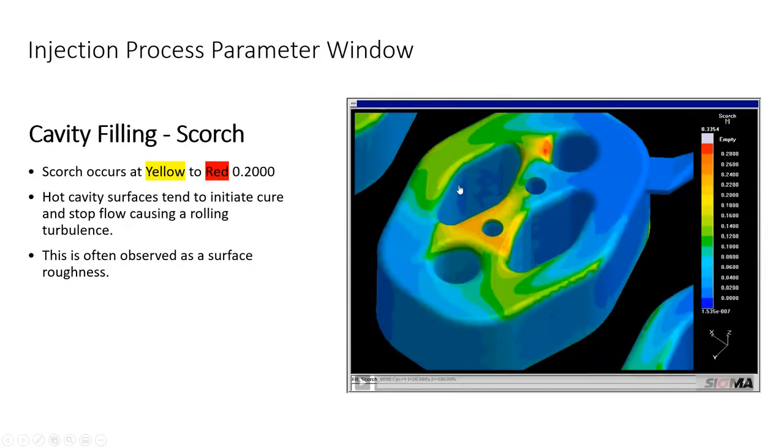So again, we can make some changes to the rubber cure states by slowing down the cure. If it's an organic, we might want to change the accelerator levels. If it's a silicone, we want to change the type of peroxide, or add inhibitor if it's a platinum cure system. There's a lot of things we can do from chemistry.